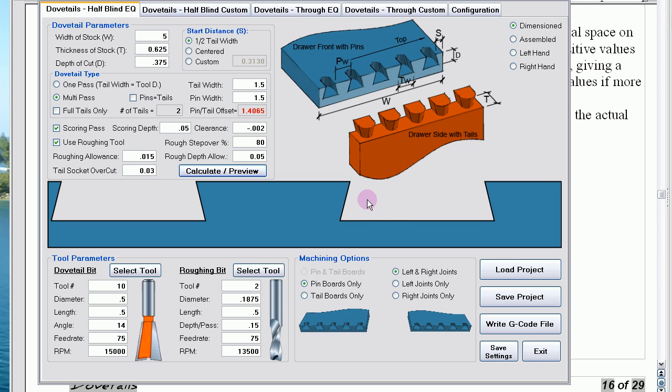Typically your actual step over is going to be smaller based on the type of tool path required. You might have an extra pass needed as the tool has to enter and exit a certain number of times. An additional pass is possibly added, and the step over might be slightly less than the specified. So think of the step over as a maximum number. Next item.